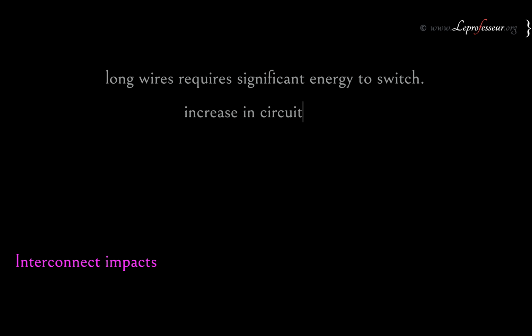The second thing is that, as we saw earlier, long wires introduce resistance and capacitance, and in other words, that introduces delay. So overall, that increases the circuit delay. There are also crosstalk delay effects due to coupling capacitance, and crosstalk delay effects due to inductance and other inductive effects.